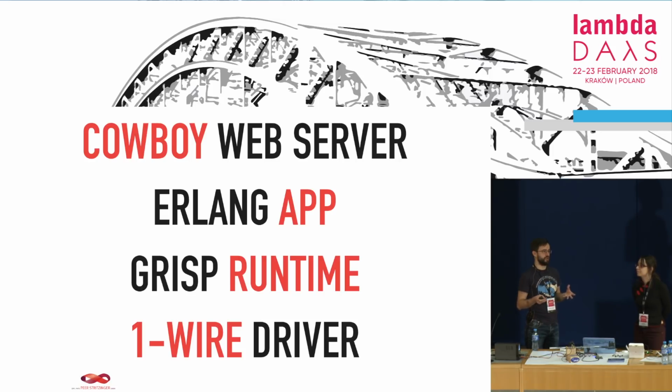And in the Erlang application, we're using the GRiSP runtime to use the drivers. We have a one-wire driver already in the GRiSP runtime, and we have a high-level Erlang driver for these temperature sensors. The Erlang application for the prototype for the demo is basically wiring all this together. It runs a regular scan on the one-wire bus to see if new temperature sensors have shown up. Whenever it finds a new one, it will start an Erlang process that will regularly query that specific sensor with its own unique ID for the temperature. And then when the WebSocket updates, it will ask all the temperature sensors that are available what their current temperature is, and then ship it off to the front end regularly as updates come.